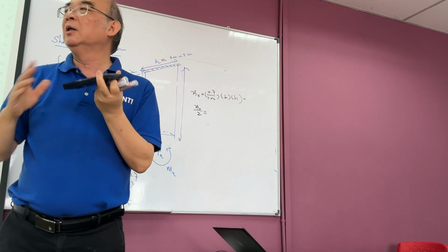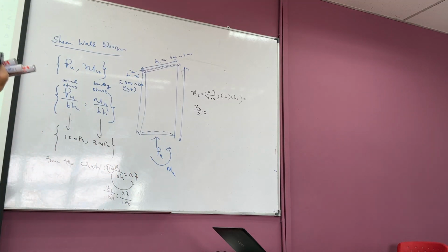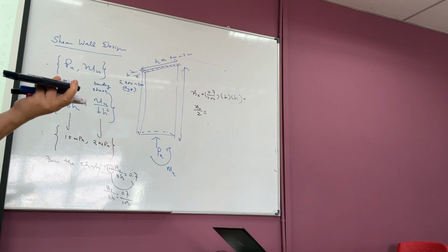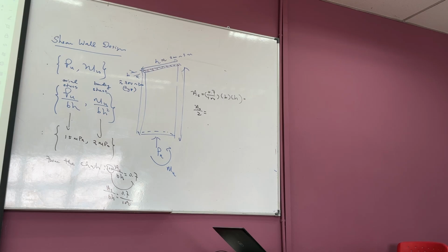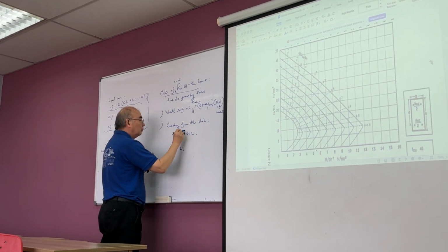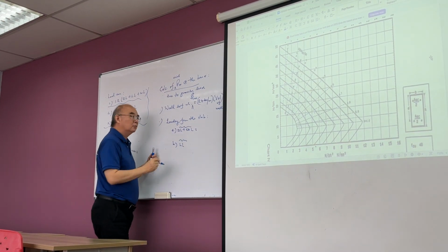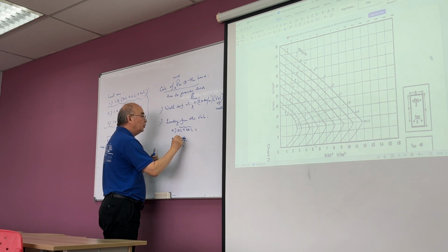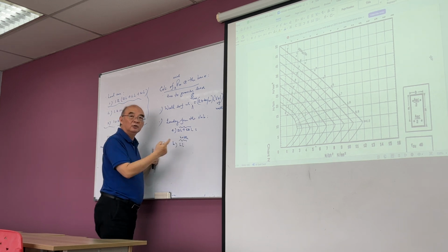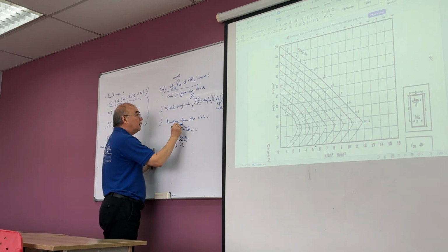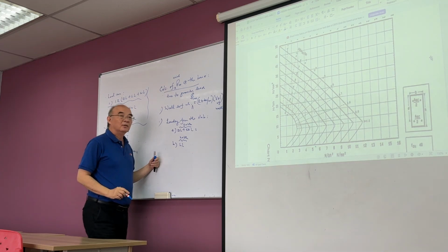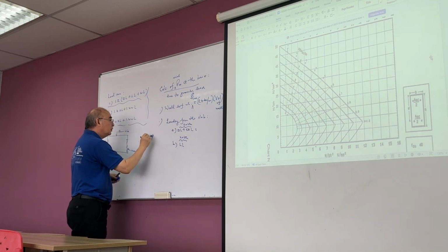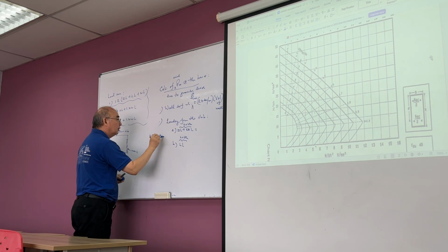Superimposed dead load will be, let's say, your tilings, which are not going to move, your ceiling, which is not going to move. So here normally this will be given to you as area load. Let's say this is 2.0 kilonewton per meter square, and let's say this is 6.0 kPa. Understand? This is kPa, meaning it is area load, kilonewton per meter square.